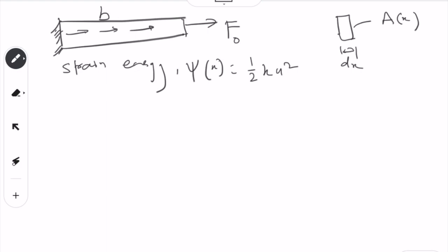So if you want to find out A, it is given in this section, and Young's modulus we also know, right. Okay. So if you want to find out the strain energy, we have to see what is the stress and what is the strain. So this is the equation; then we have strain here and stress here, and accordingly we take the area of that. So simply this stress times strain will give you the strain energy.